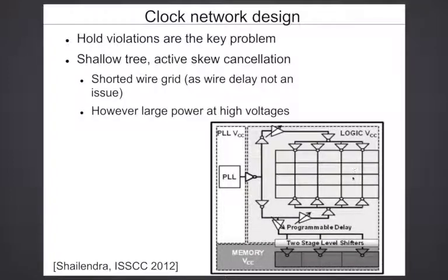They used a clock network like this, which was like a grid, but the whole clock network consumed 50-60% of the total chip power just to deliver the clock, because you have a lot of capacitance like this. So people moved away from this way of designing clock networks for processors, and you have more of a clock tree and fine tuning of the clocks, such that you still get low skew but